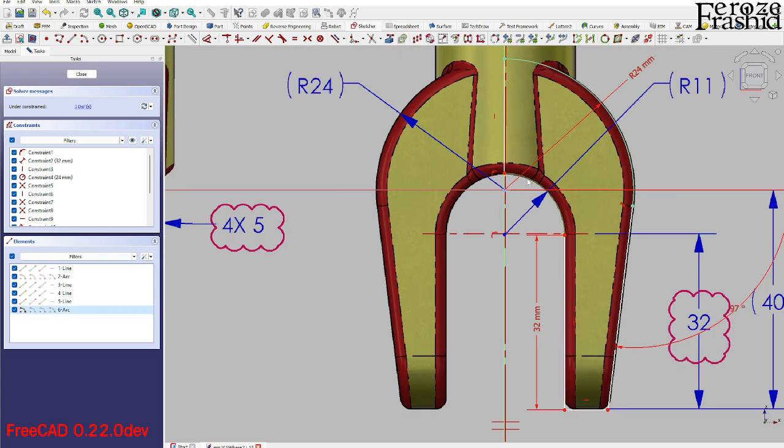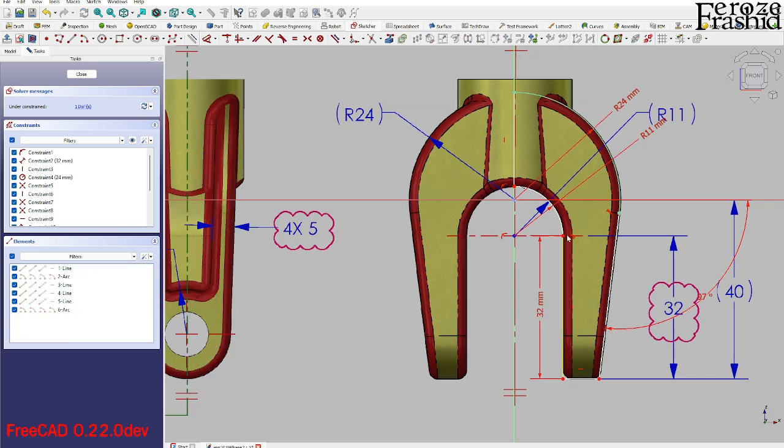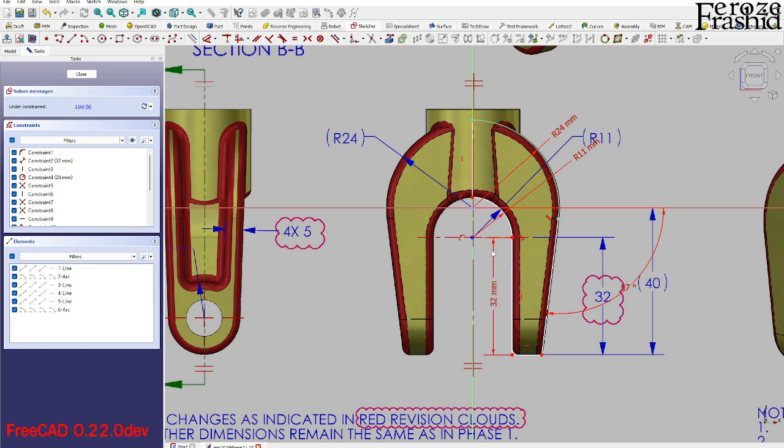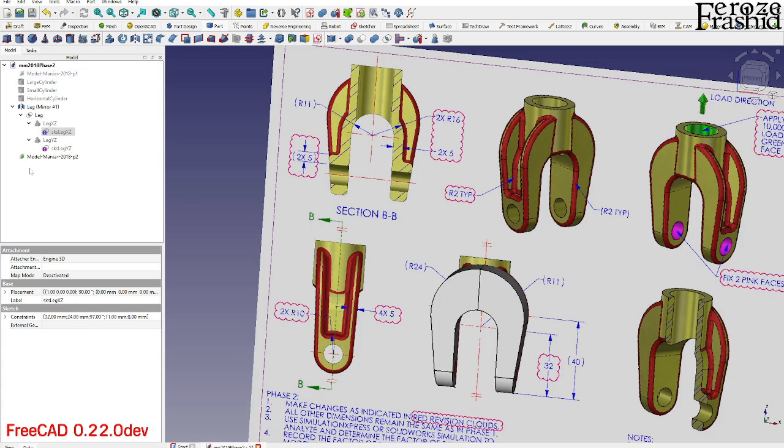and now we can go ahead and say this radius is 11, and I can say these two would be tangential, right? Things are moving here, and I can say that distance between these two centers is 8. So let's take this and apply an 8mm constraint. So the first sketch is updated. Let's keep it that way.